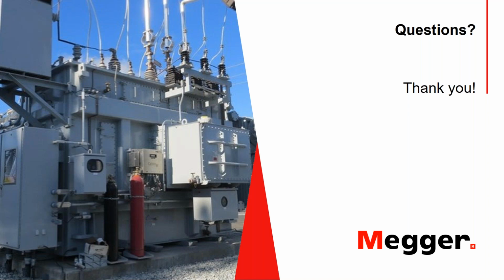So that's a really good question. And if you review industry standards such as C57.152, they do mention that caveat, that understanding the previous magnetic status of the transformer is really important before you begin testing. And from a testing sequence, if you can perform all your tests before winding resistance, that's better, because then after you perform your resistance measurements, you can completely demagnetize the core, and then you're ready to move forward with your next step.